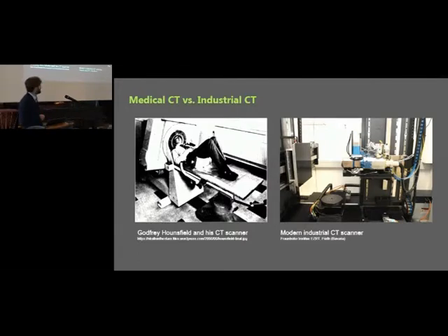We have the X-ray source here, we have a turntable here, and this is the detector, and we can adjust the whole machine, while this machine is only optimized for human bodies. So in this tube, there's a detector and the X-ray source rotating around the body, while the object we want to study is placed on a turntable in the industrial machine, and the object turns.